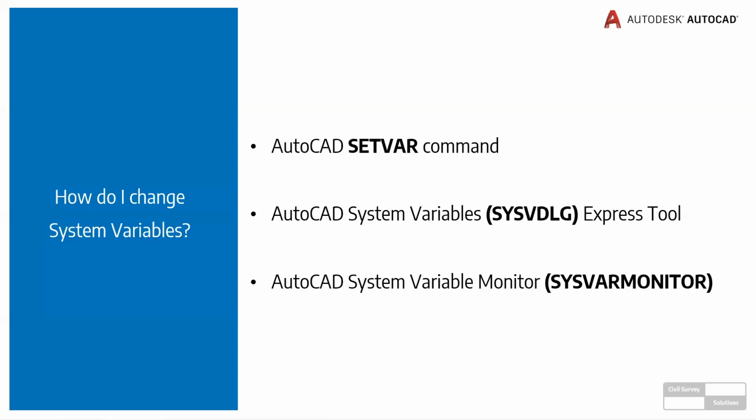I'd recommend placing the ones that you rely on in the system variable monitor, and then you'll be able to see if it gets changed. And then you can reset it to your preferred setting if you want, and it's easily done in that system variable monitor.